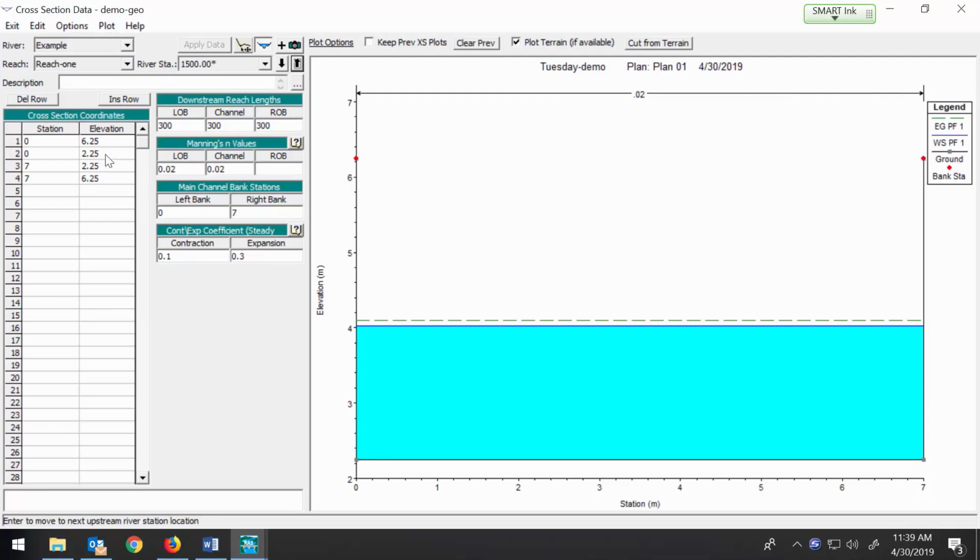In just a bit, we'll take a look at copying this data and pasting it into a table. But if we're just visualizing things through the cross-section, the depth of the water is from the bottom of the channel up to the end of the blue. All right, so it was 3.8, and now it's down to 1.75 about.